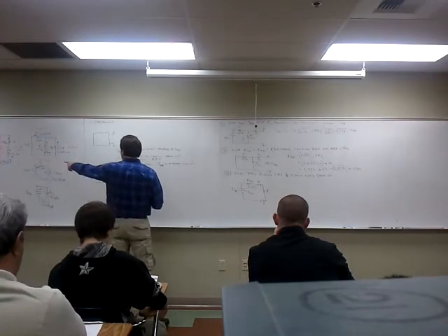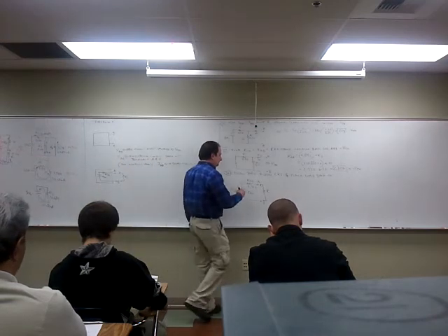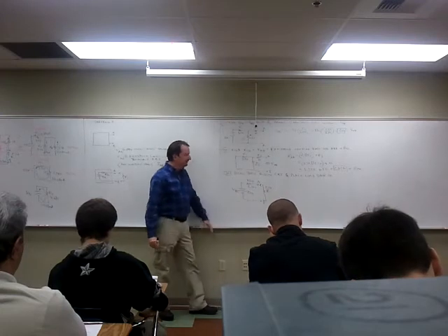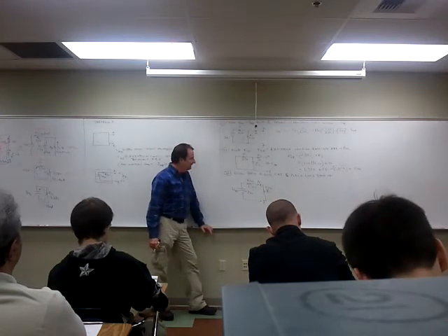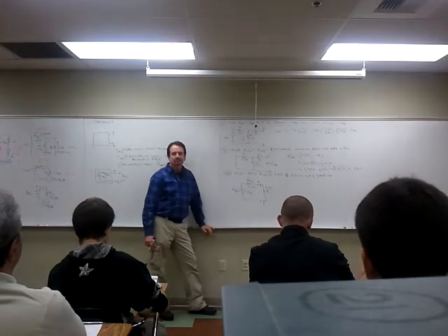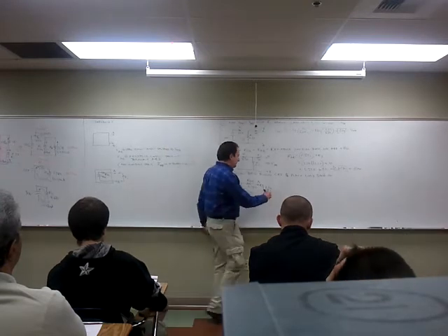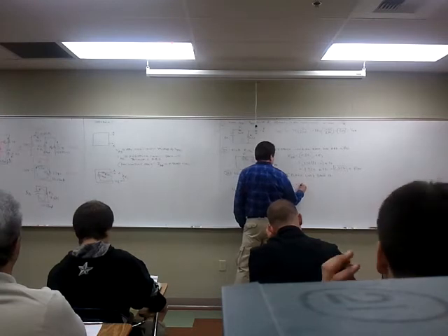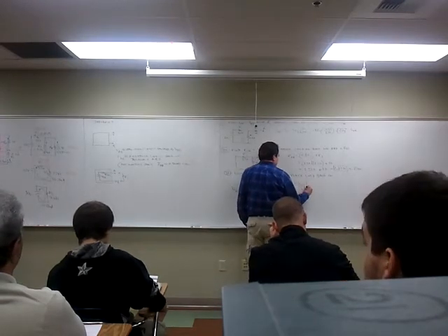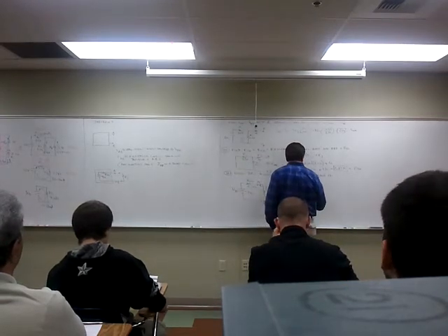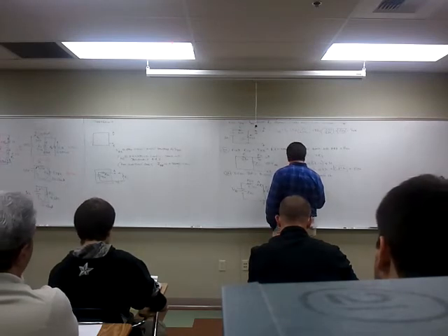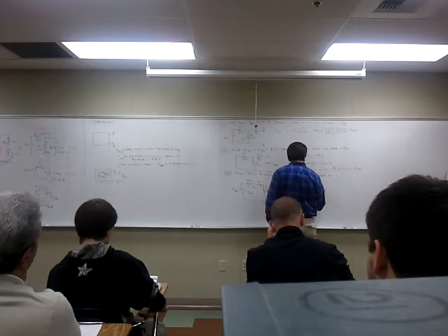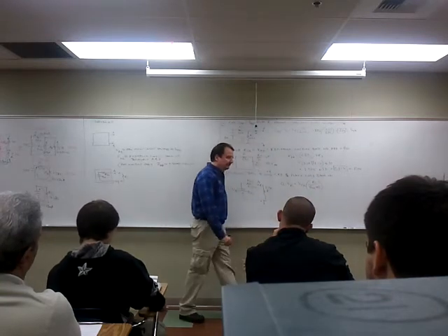And our RL was 2.7K. Now with this little circuit, can I now find the voltage drop across RL? Sure. The voltage drop across RL is equal to the total voltage, because we can use voltage divider equations, can't we? Total voltage times RL over R Thevenin plus RL. Now, can you do it by normal series circuit techniques as well?